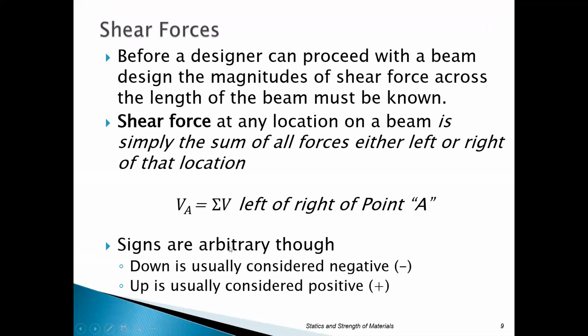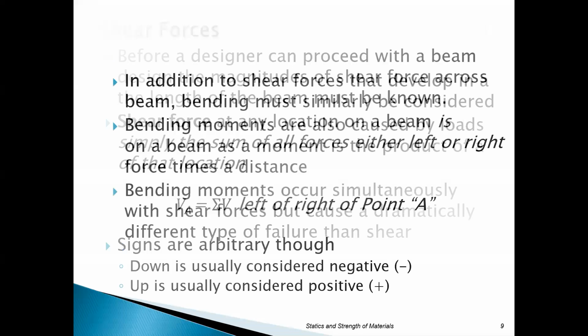Okay, so all we're doing is this equation. The shear at any point is the sum of shears left or right off of that point. Okay, and again, we usually walk across the beam left or right. Again, that doesn't matter, but do keep in mind the shear at the same point, left or right, is going to be different. Okay, because your loading is going to be different left and right, unless you have a symmetric situation. That would be the only time it's not. Okay, and that may not always be true.